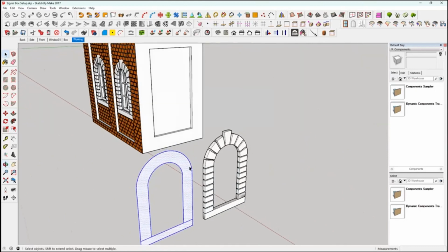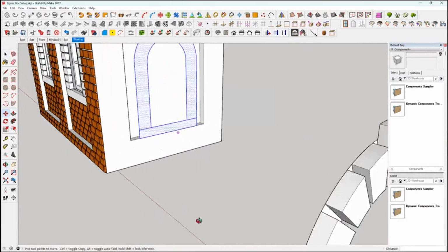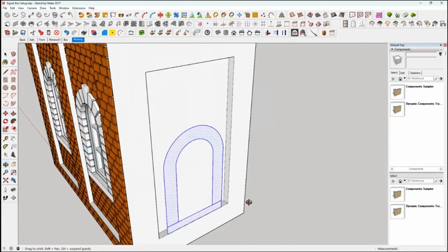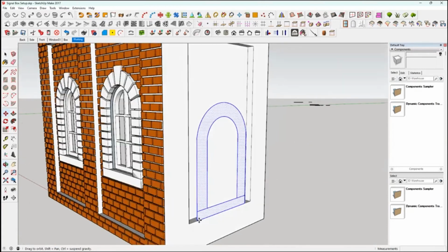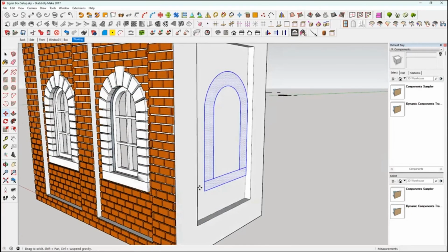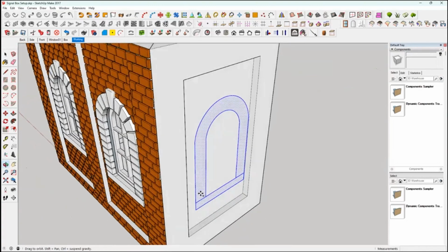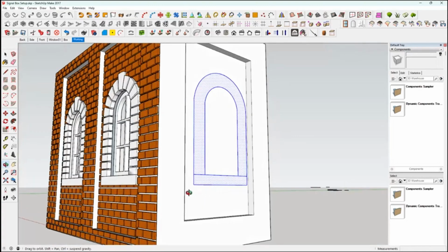So what I want to do is put this on the wall there so we can click on it. We'll find the middle bottom and we'll bring it across. And then easy enough, done. We're in the middle there. And then we can just line this windowsill up with this one. So if we click on the corner and strain it to the up arrow, and we'll click on there, and that's the same height as that. And I think we've got to go in against the wall. So we click on and we go along the red axis, touching the wall.